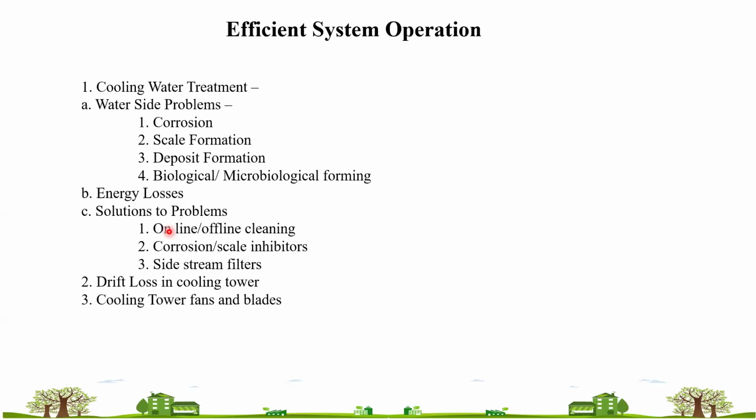So if you are saving 5 kilowatt of power or 2 kilowatt of power by optimizing the fan power, you are losing much out of there inside the utility. So you need to be very cautious while doing this kind of projects, or while suggesting this kind of projects to any company while doing an energy audit. So we have to be very cautious to understand the application.